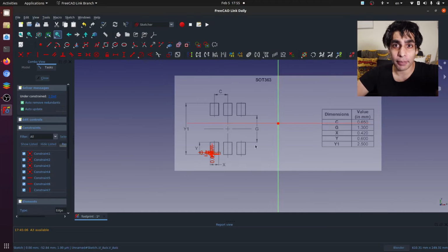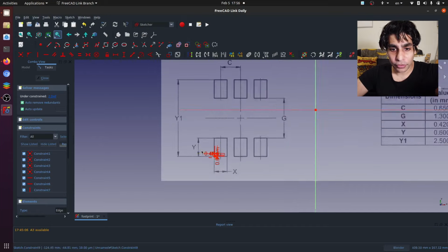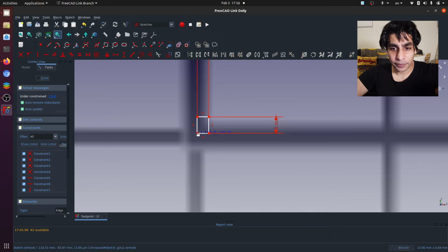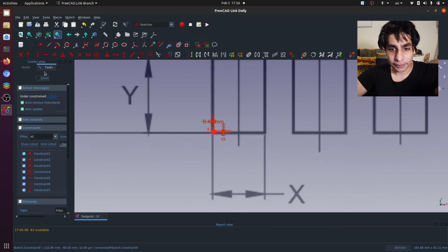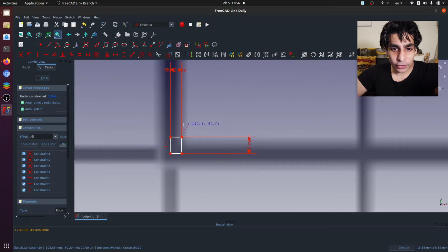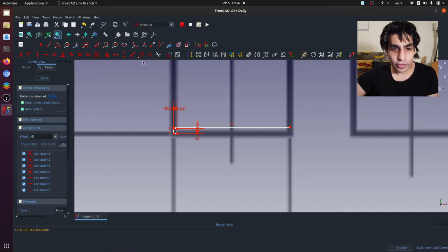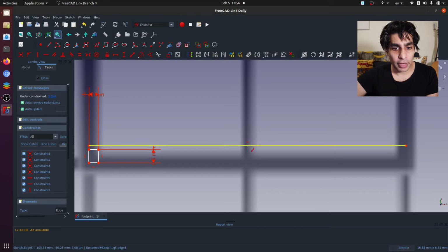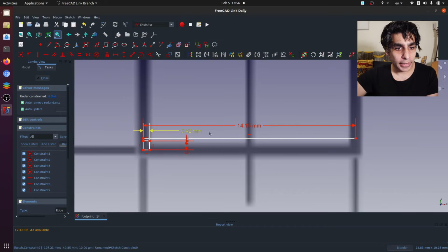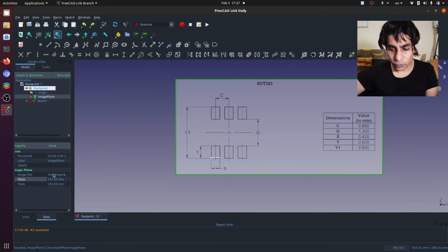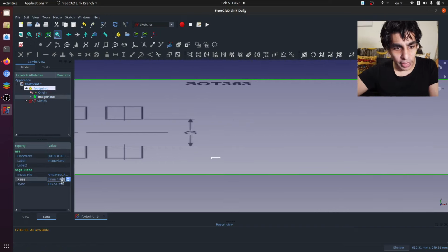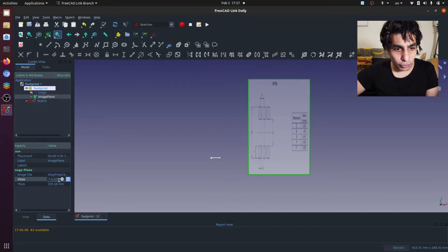So what we need to do is scale the template down to the correct size. What we'll do is we'll place this part in the correct location, and then we'll create a reference line. And the goal of this reference line is to basically help us understand what the current scale of our template really is. So from here, we'll just remember these numbers, 14.15 and 0.42. And we're going to go back into our image, and we're going to modify the X and Y size, 14.15. So multiply by 4.2 divided by 14.15. So that should scale our dimension, but we want to scale it evenly.